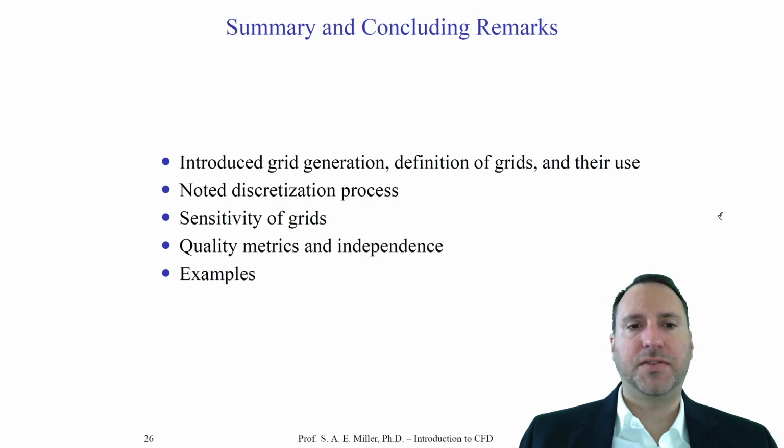We also talked about the so-called sensitivity of grids and the grid-independent studies. These are critical for showing that you have a true solution of the discretized equations. The solution must be grid-independent. If the solution is not grid-independent, then it is not a physical solution of the equations of motion. Finally, we looked and went through a bunch of quality metrics for you to judge with your grid generation program to see if you have a quality grid. You should report these in research papers if ever writing a paper on CFD, or in presentations of CFD if you're working in a company.